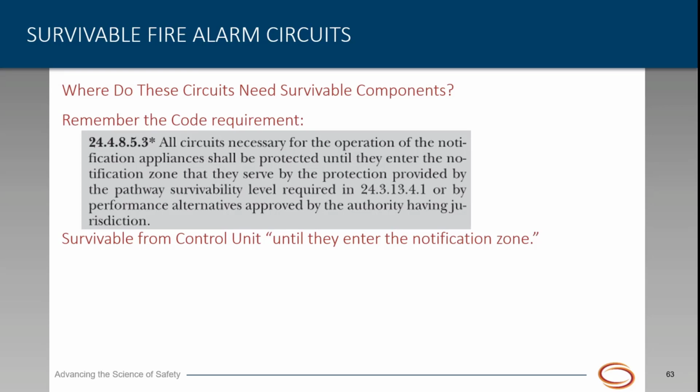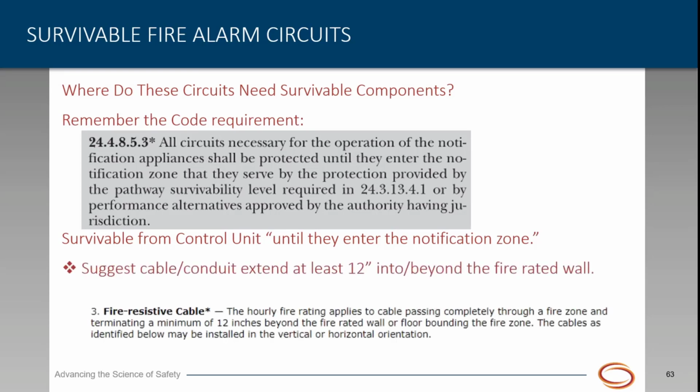In this case, it just means what it means. As to how far, I suggest at least 12 inches into or beyond the fire-rated wall. I take this obviously from that UL documentation where it requires the distance of 12 inches, although NFPA 72 itself is silent on the matter.